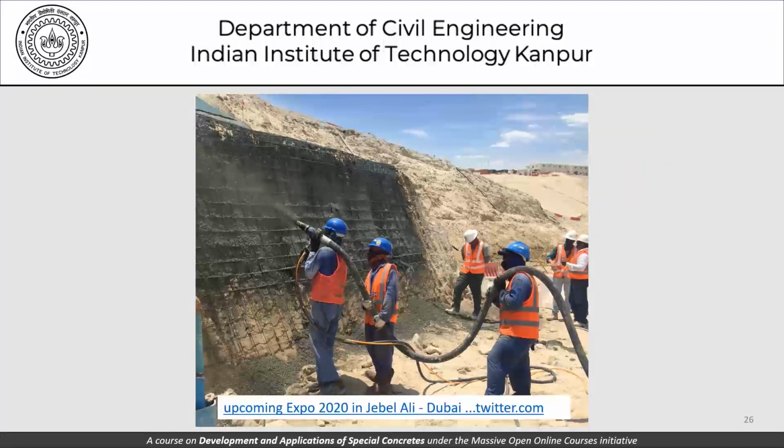We can see this reinforcement which has been placed, and we are trying to place this concrete here against the slope. No formwork, and we are expecting that as far as shotcrete is concerned, this is the reinforcement that we have placed, and let us say it is placed somewhere here, and this is my surface. So if we are gunning it here, the concrete is expected to reach all these places at the back and have a deposit which will become something like this with reinforcement bars somewhere here.